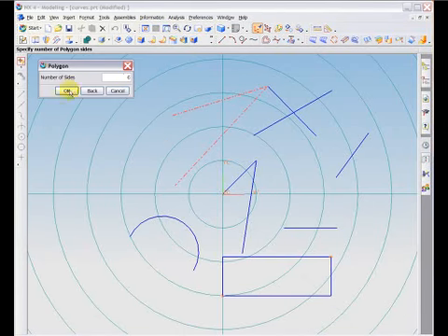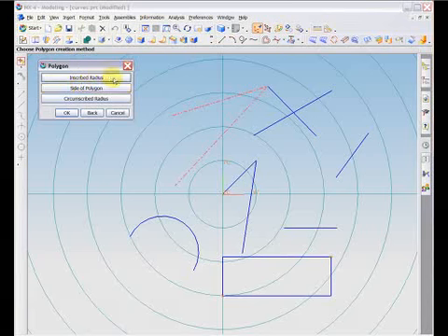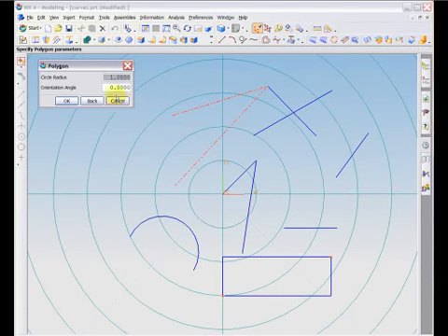You can either define the radius of a theoretical circle in which it could be inscribed around, the length of one side, or the radius of a circle it would be circumscribed within. After you've selected an option, you must choose the dimension value as well as the orientation angle, measured counterclockwise in degrees. The default of 0 will orient the polygon with a corner at 0 degrees to the x-axis. Then, simply choose a point for the center of the polygon.